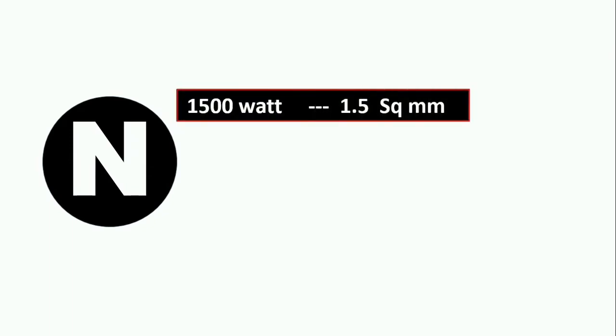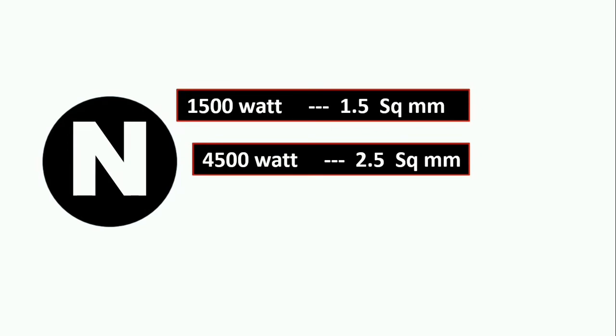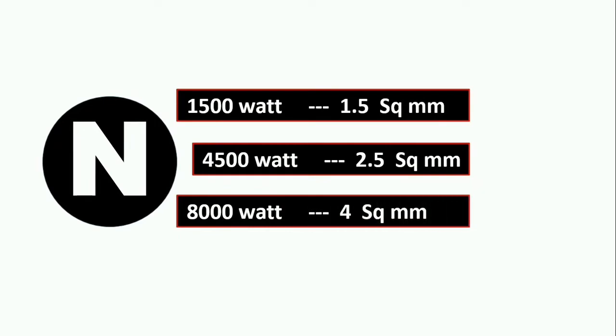Now, for your neutral cabling, you might want to use 1.5 mm for neutral lines on your neutral bars. Maybe your neutrals can all be 1.5 mm, but depending on the wattage, like I said. So if you're trying to give a neutral to a socket outlet, you should use around about 2.5 and above.